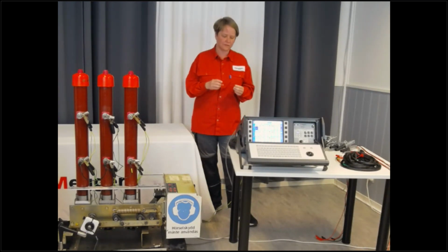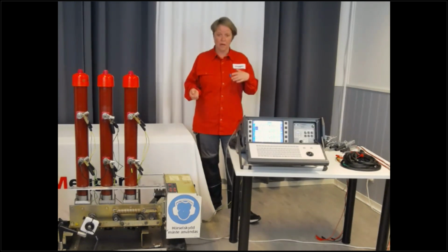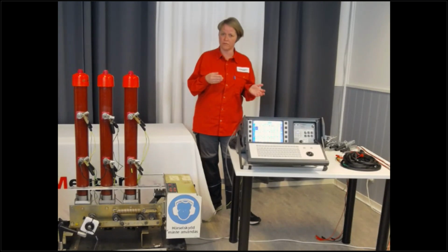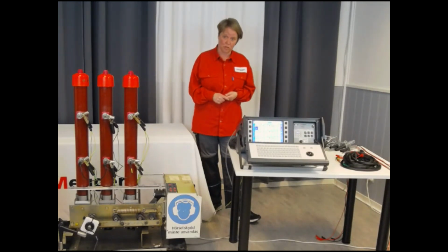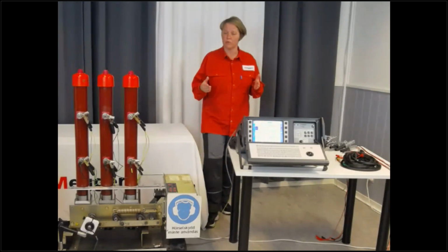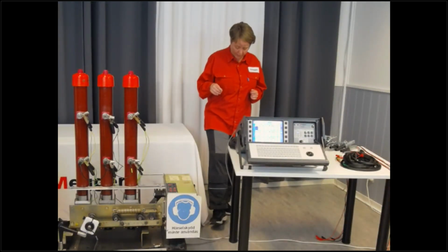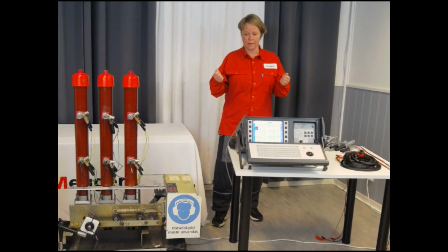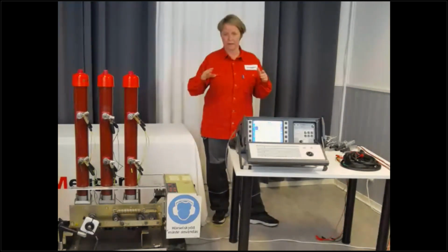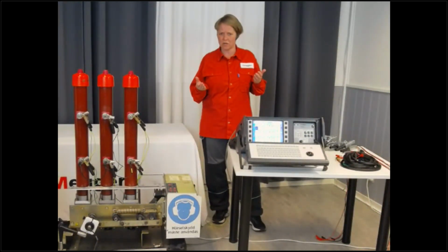Ferrite, what is that? That is like an inductor you can snap on the grounding device. And when we mention that, it's very natural to go over to these gas-insulated switchgears. Sometimes you have real trouble measuring those with normal timing, because you can't ground them separately, and the only place where you have access is commonly the grounding points. So again, we have a common ground part.